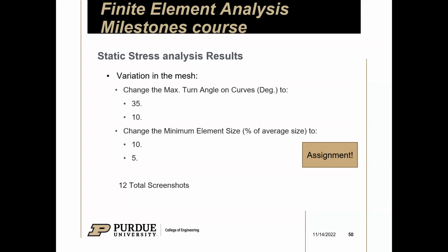What does the max angle mean? What it really means is, I believe, how tight the angle of the triangles is. So when you lower the angle of the triangles, you can fit more triangles along the surface. If you have a triangle like this, this angle is the one that's decreasing. When you decrease it, you can fit another one side by side, put them upside down, taller. Basically it's around the edges, that kind of stuff. So it helps analyze that.